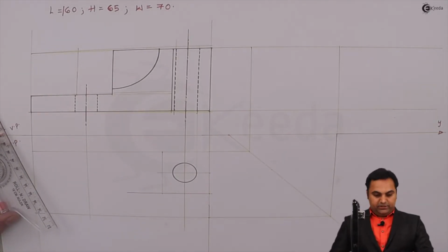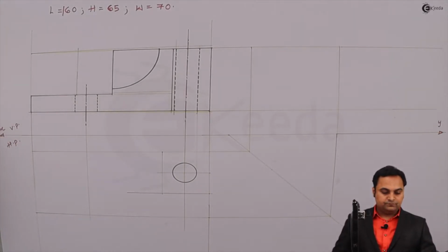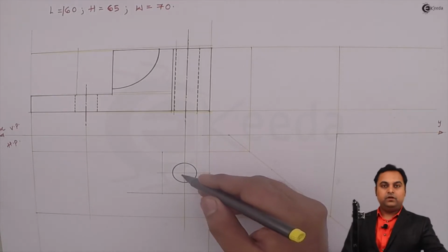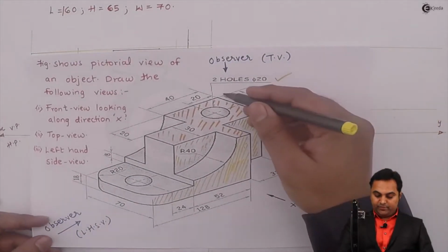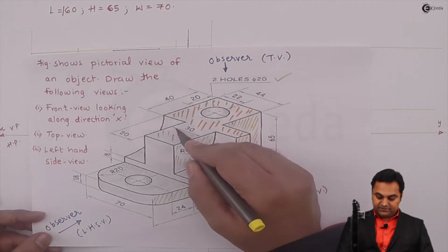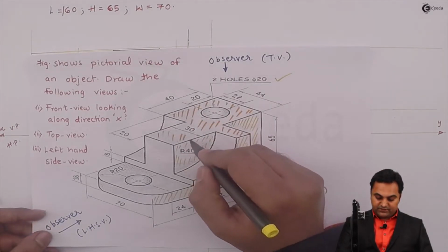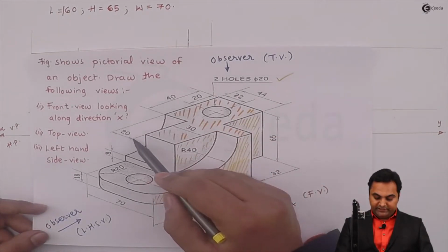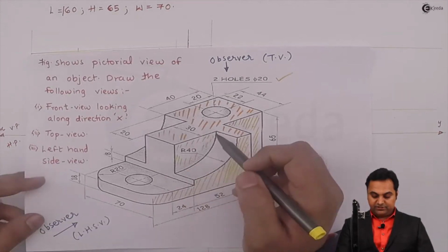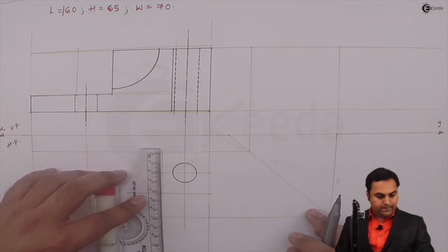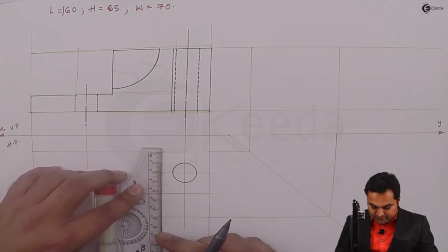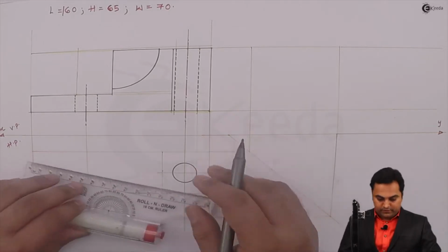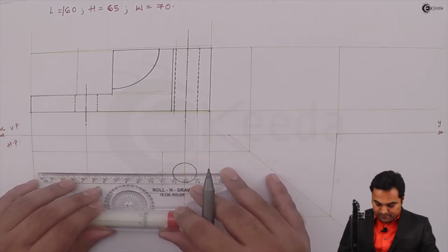Next, after reaching up till here, from this center, that is up to 22 mm width, from this center there is a distance of 30 mm as we see here, or in other words I can say that after taking 20 as the width, next I'll measure 30 width. So over this 40 I'm going to measure the width as 20 mm, and then drawing a light horizontal line through it.